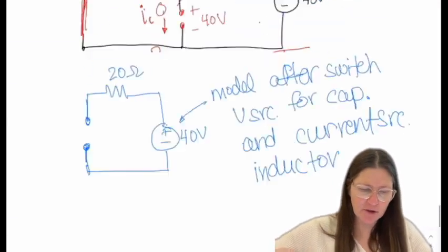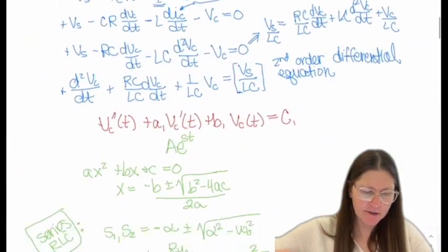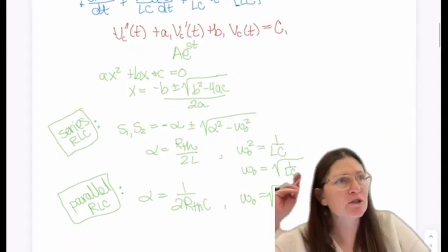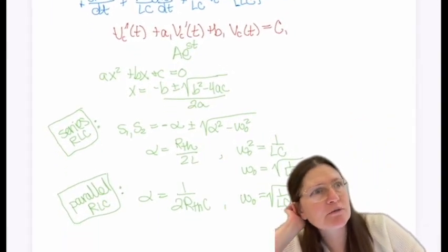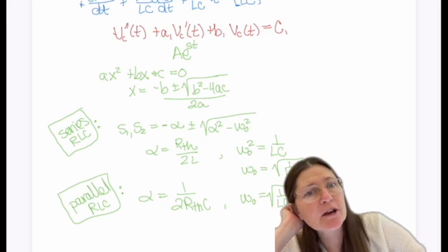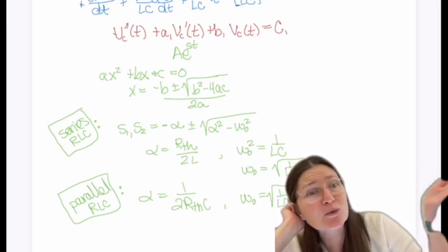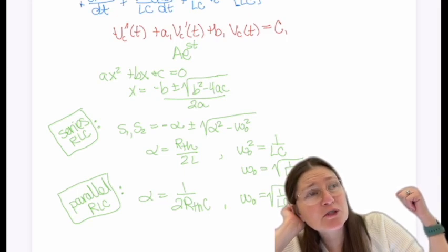So when we solved the RLC equations, and we turned them into that second order differential equation, and then from there, if you substitute in, like, the differential as a variable, like x squared, it looks like a polynomial. You can solve those then for that polynomial form just using the quadratic solution.